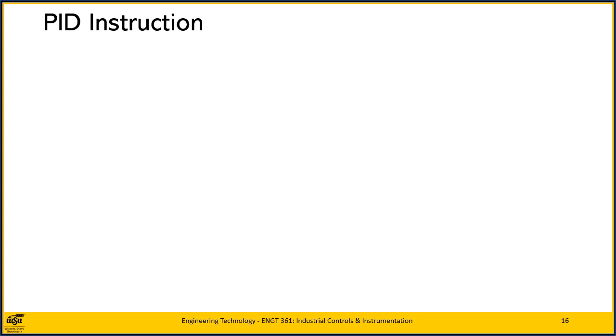PID control is becoming more commonly available on PLCs. In most cases, the PID function is implemented by an instruction and uses regular I/O analog channels. Another possibility is a separate PID hardware module, in which case it is actually an independent operating controller running under supervisory control of the PLC. The PID instruction implements the PID control strategy discussed previously in Module J. It would be used in a closed-loop system to control some physical parameter such as temperature, liquid level, or even motion, although a motion problem may require faster responses than the PLC can deliver.